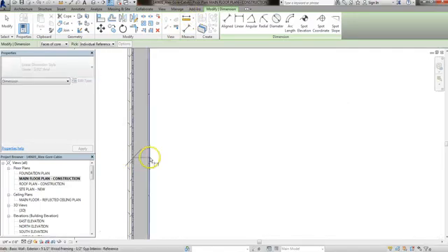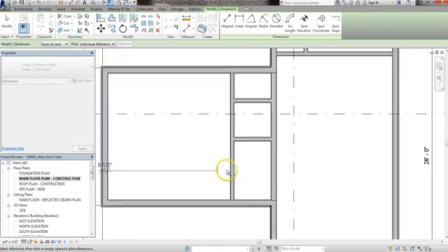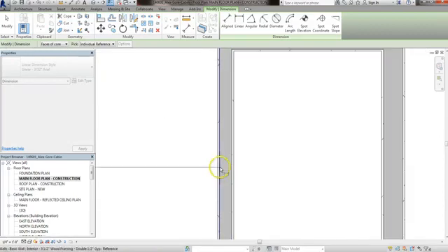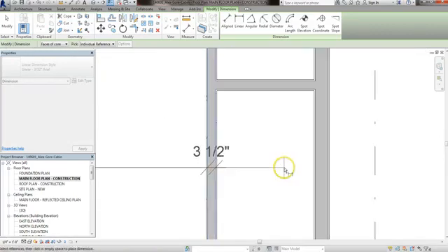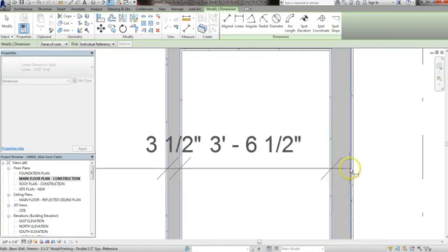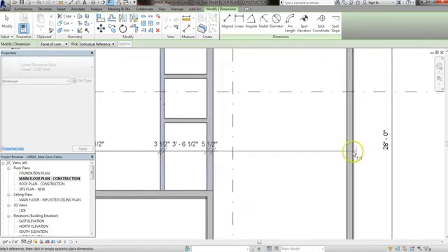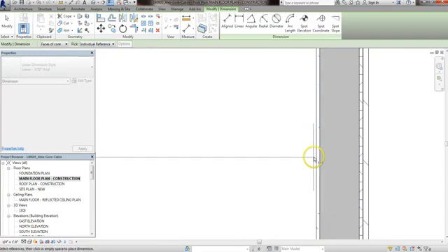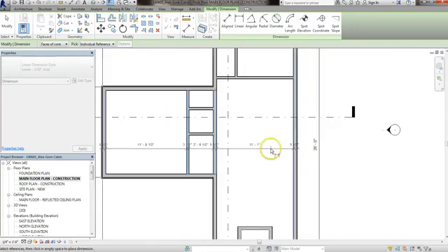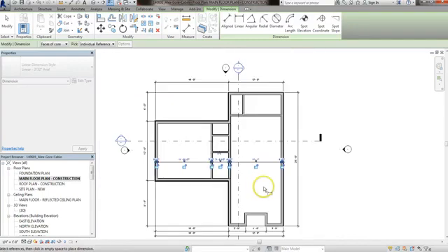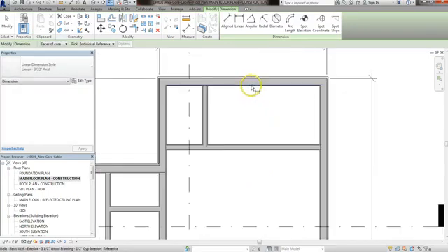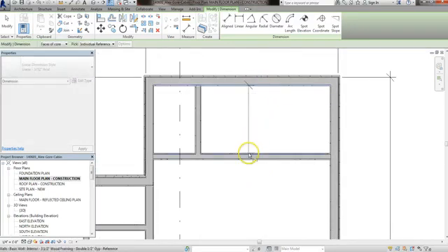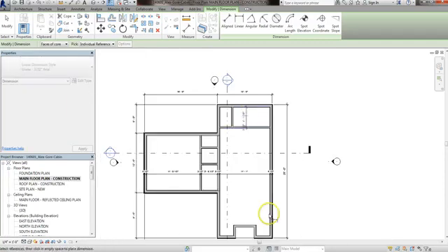What we like to do is we like to make sure we tell the contractor how big his studs are and the carpenter. So we click on the edge of framing. This is your gypsum. This is your framing. And after we're done drawing that line, we just click anywhere, and then it releases it. You can do the same for these walls.